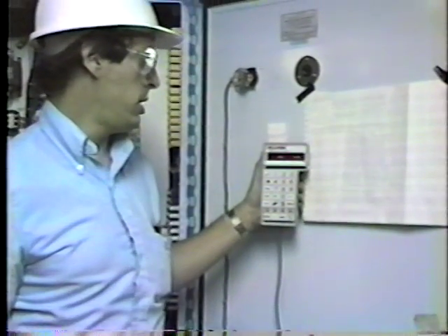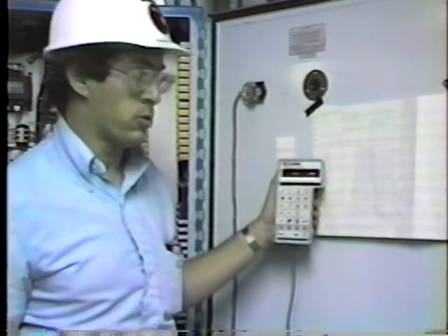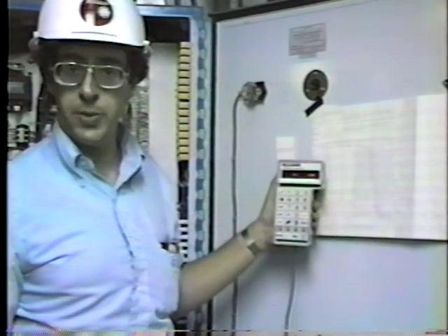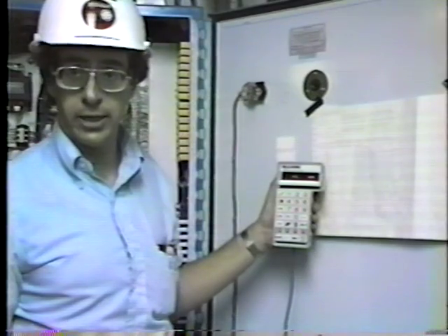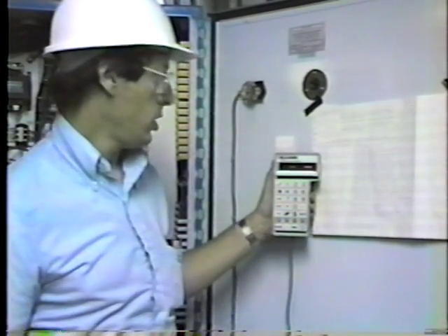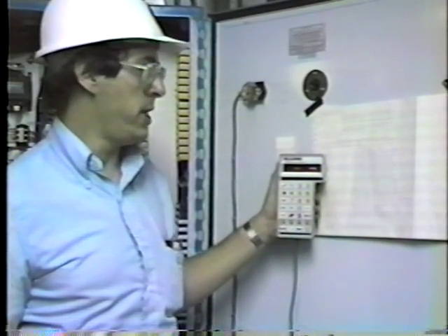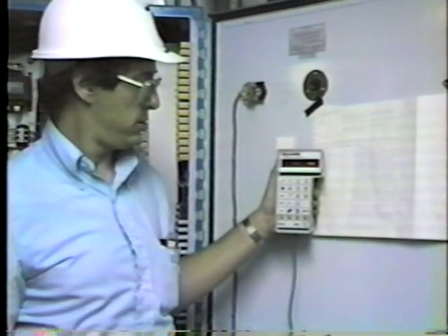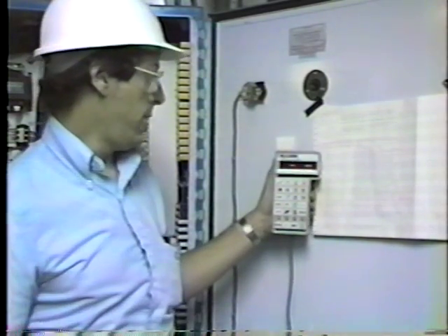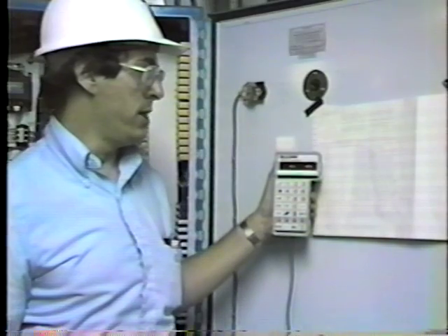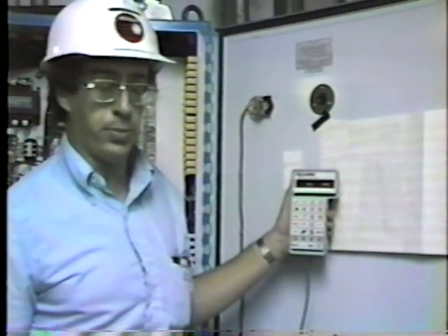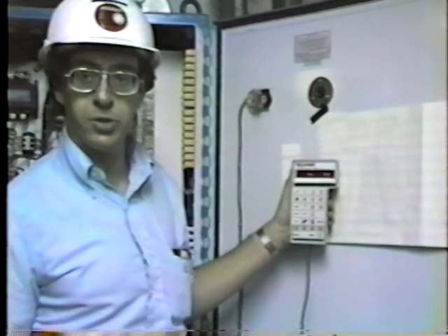Number 16 is the feeder speed maximum increase. This is the amount of topside feeder speed correction that we allow from the target. It's set to 10%. Number 17 is the feeder speed maximum command. It's set to 99%. Number 18 is the maximum allowable milliamps at maximum mill speed. We haven't set that, as you noted above, and so that's still set at 99%. Okay.